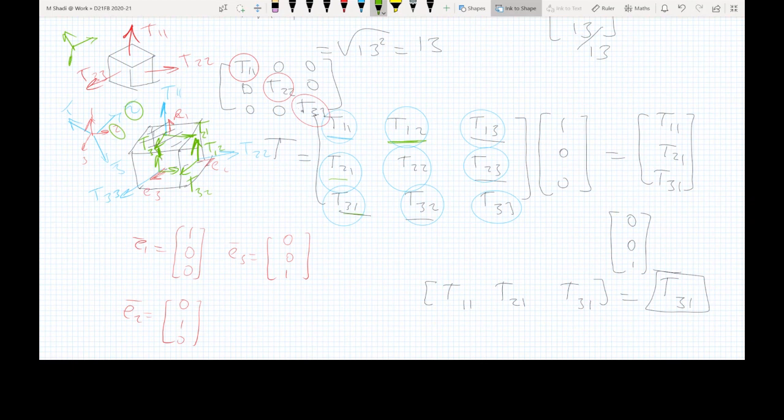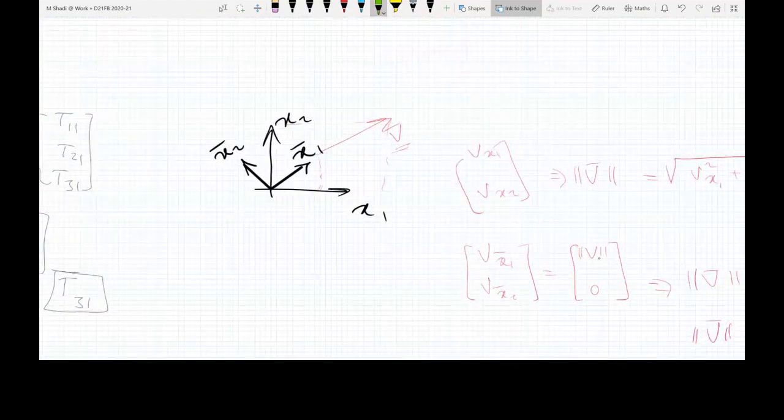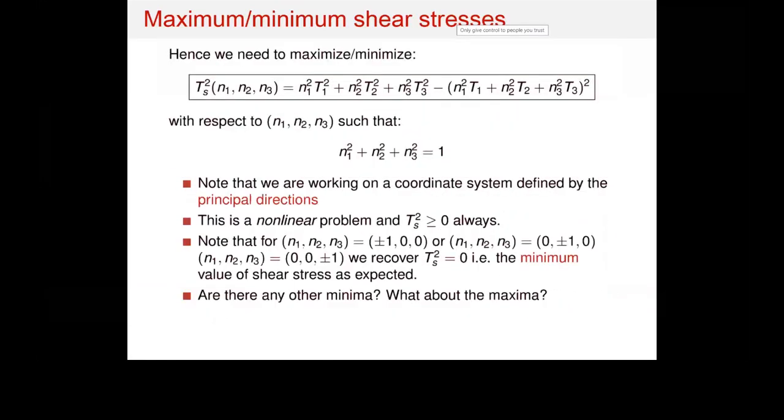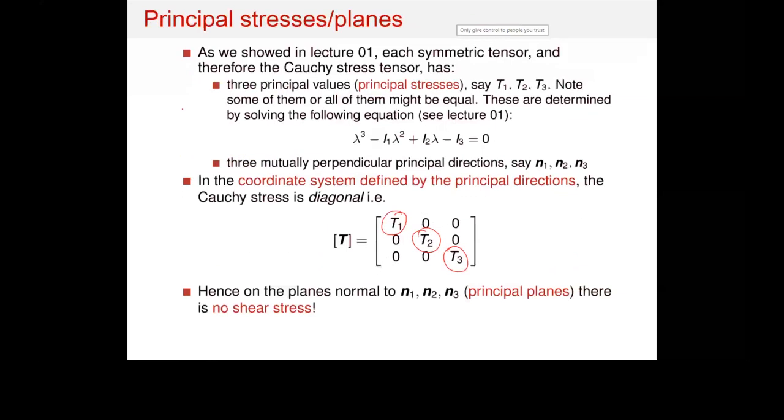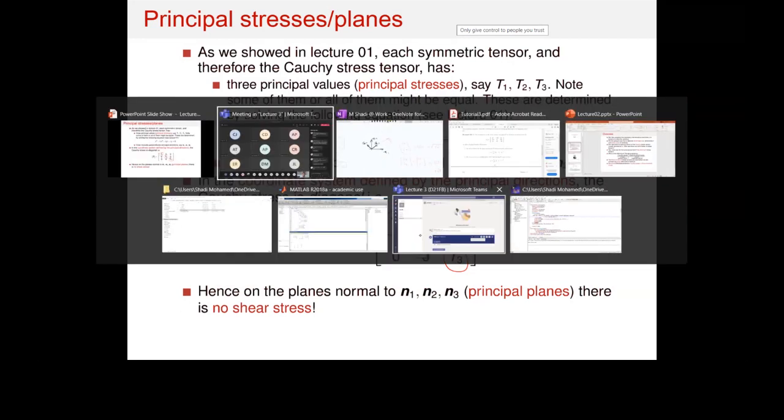So this is going to be the maximum normal stresses that would ever happen because of this stress tensor. There is no way that this normal stress is going to exceed that. Just in the same way, there is no way that you will get the component of a vector to be larger than the entire length of it. So if you go back here and you want to find these maximum projections, you need to find the eigenvalues. So this is the eigenvalues and the directions of them.